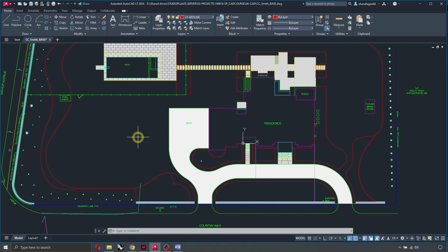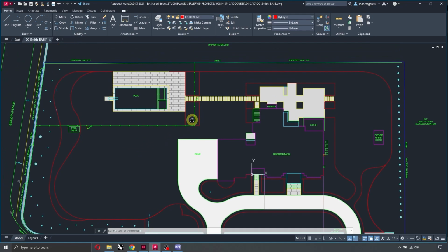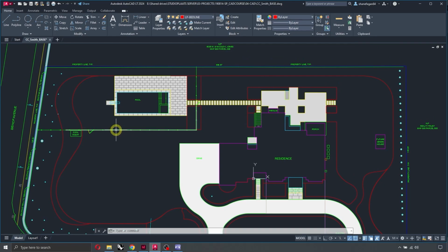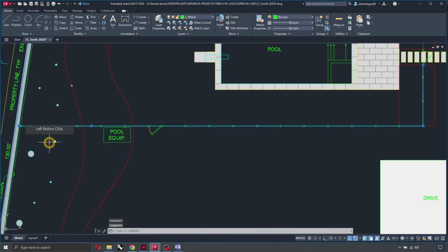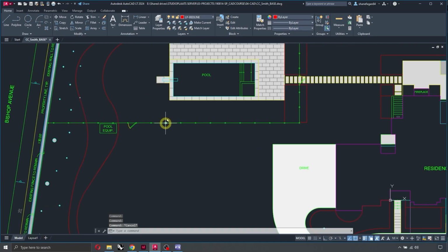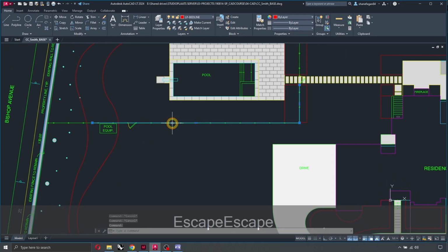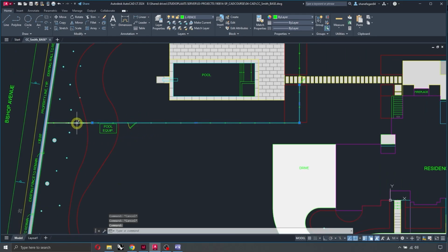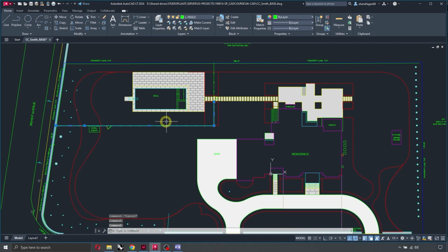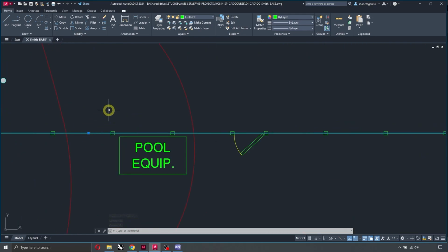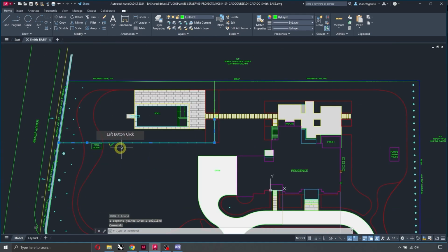I was going to show you some other ways of doing this. For example, let's select a nice line in here. These aren't connected. Okay, so here you go. Here's the first example of something that should have been drawn a different way. I'm selecting L fence. I wanted to get this portion's length, but they're not connected here. So I'll type J, to join into one polyline. Now this is all one line that turns.